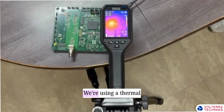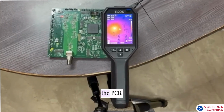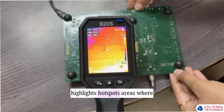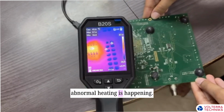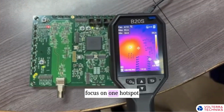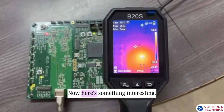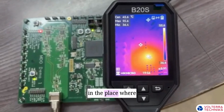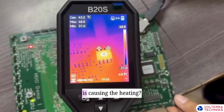Here's our setup. We're using a thermal camera to monitor the PCB. As you can see, the thermal image clearly highlights hotspots, areas where abnormal heating is happening. Now let's focus on one hotspot that is highlighted on your screen. Now here's something interesting. When we look at the PCB, we do not see any component in the place where we saw the hotspot. So then what is causing the heating?